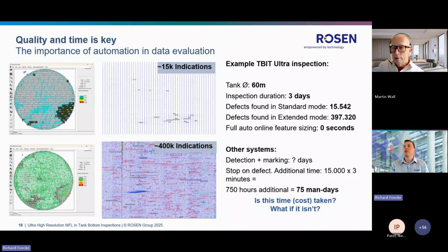That's a good question. With the implementation of the ultra high resolution, we thought we should also give the coating thickness and the lift-off more attention. That's why we also implemented the coating thickness, represented by plexiglass plates, in the calibration process. So during our annual tool calibration, we run the tool over all plate thicknesses, but also over all lift-off thicknesses. And that leads to very accurate calibration curves.